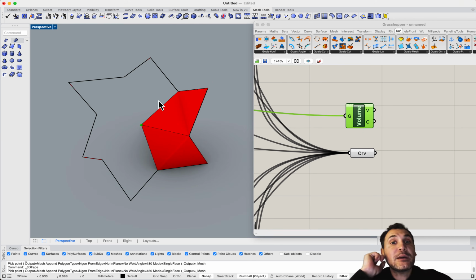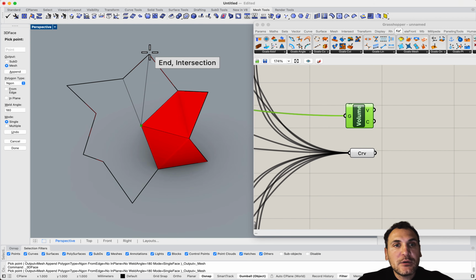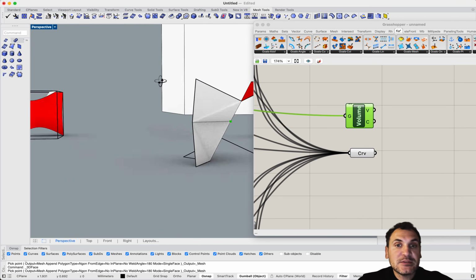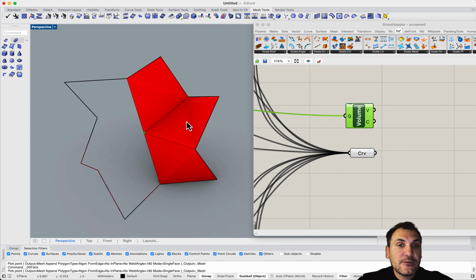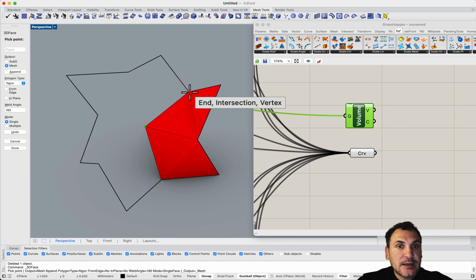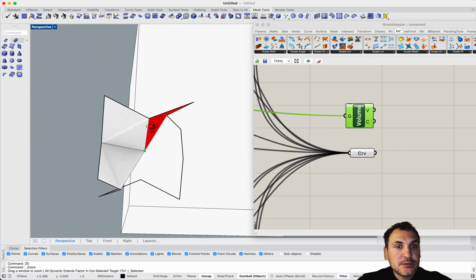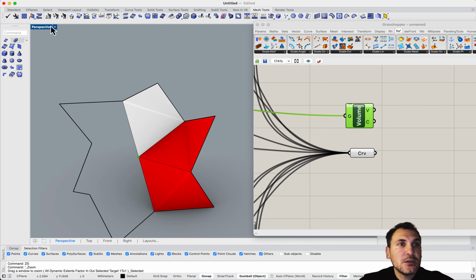And the reason why we are doing it this way is so that this basically will describe the topology of the surface. But once we smooth it out through subdivision, it will actually maintain the topology, but it will add more faces. So this line would actually become kind of curvilinear, right? So that's essential for the construction of these minimal surfaces. So you can see we have kind of 2 directions for the faces. And if, for some reason, let's say I do a counterclockwise construction, I'm actually getting an irregular direction.